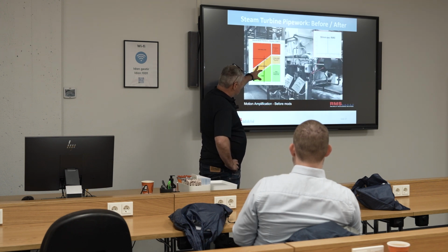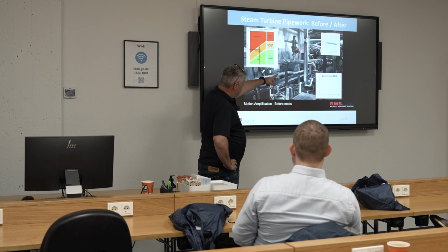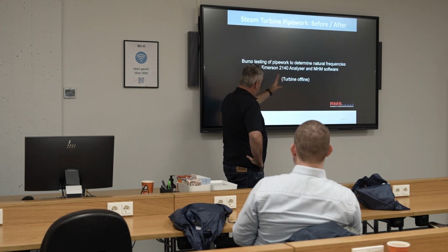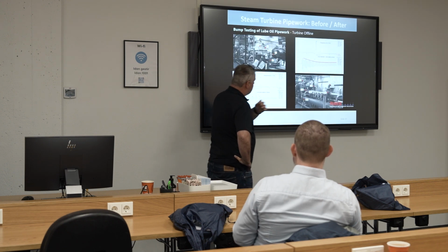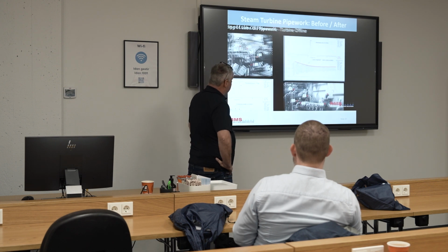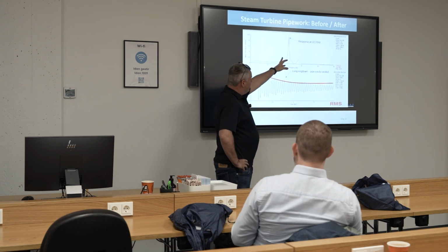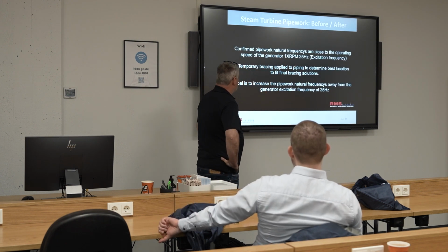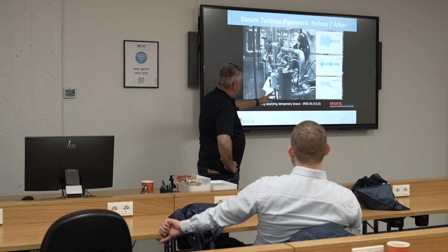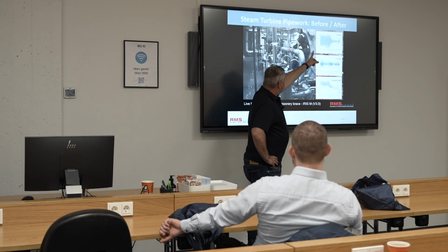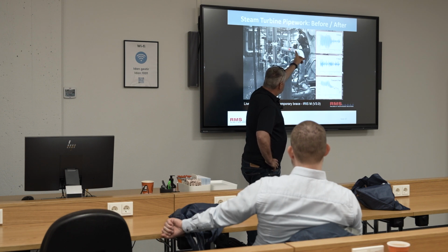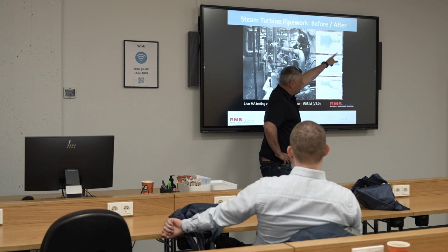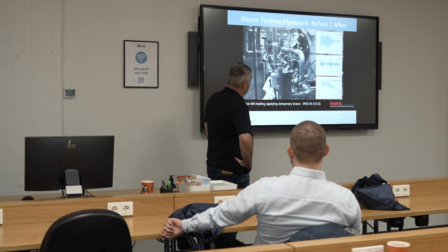And we keep reflecting this Energy Institute guidelines, and you can see the frequency of vibration. But what's nice to do is use it in live mode to determine certain situations, and you can see the effect. This is with the instrument though. We've measured this frequency at 22.5 Hertz, which is too close to the excitation force. So what we're doing there is using the camera live, and we're going to put a temporary brace in here and adjust it so you can see the vibration. And once you put the brace in, you can see the vibration come down to nothing as he's tightened the brace up.